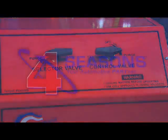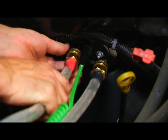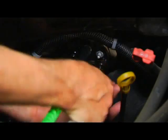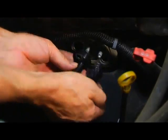You may think that the solvent would simply vaporize due to its low boiling point, but remember, it is mixed with the dirty PAG oil and will not vaporize. After the 30-minute air purge, disconnect the lines and the adapters. Remember, you can be working on other tasks while the purge is taking place.